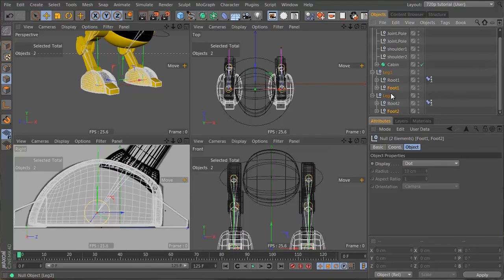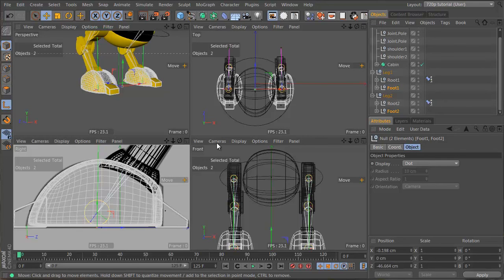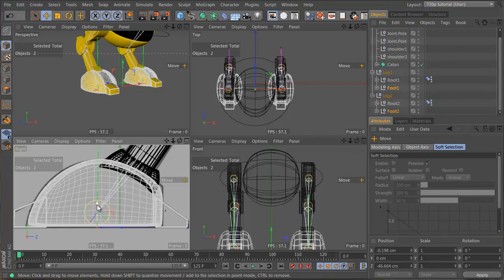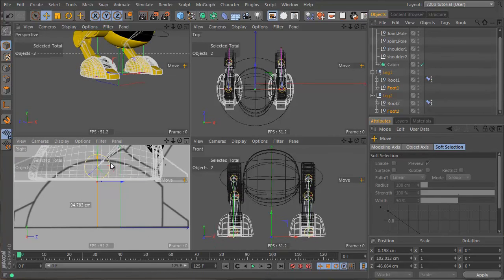And now we select both of them. We go to axis tool, which means we just move the axis, we don't move the actual foot, and move them down to the 0 coordinates. So to the ground plane. In the model tool, we can also just go and 0. So turn off the axis tool, and now move them together, the feet move.